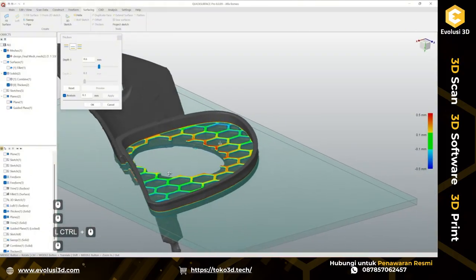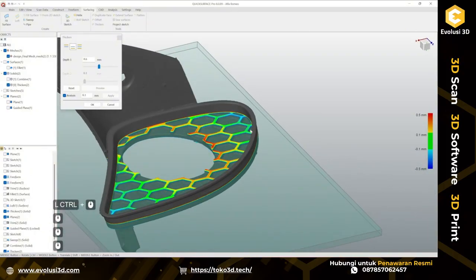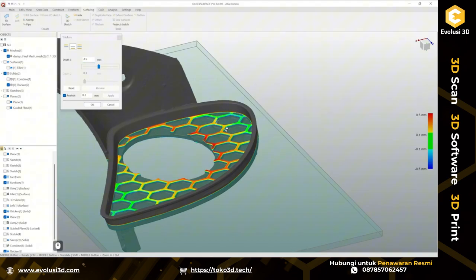And I think this is the approach that I'm going to use, not to create super overcomplicated sketches with a lot of different entities. So I'm going to thicken this plane up to, let's say, maybe 4.5 millimeters, so I catch completely these two corners.